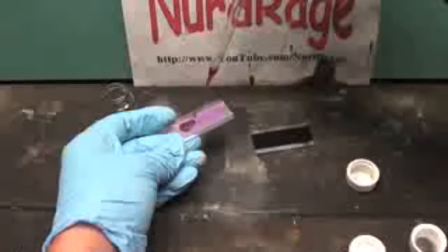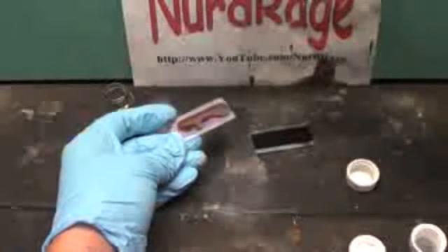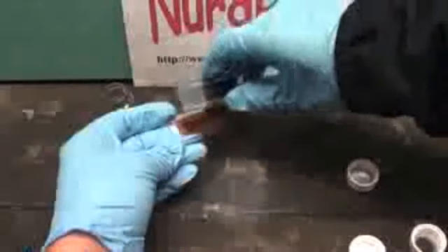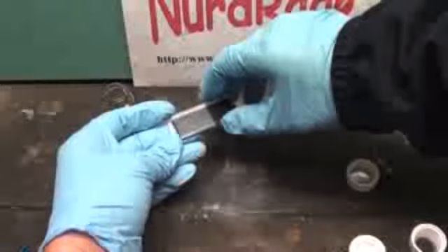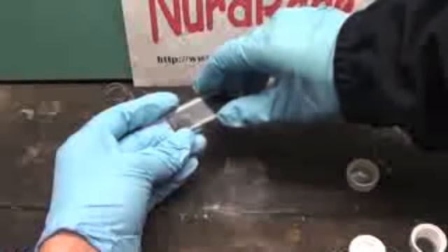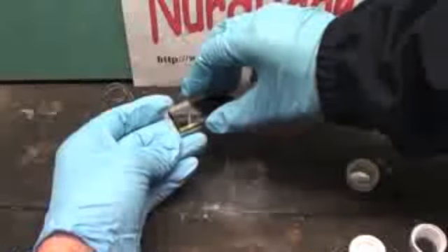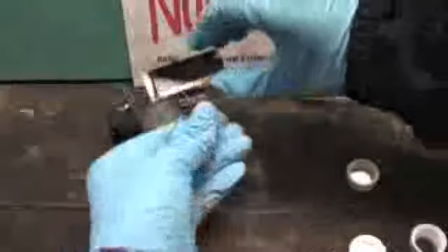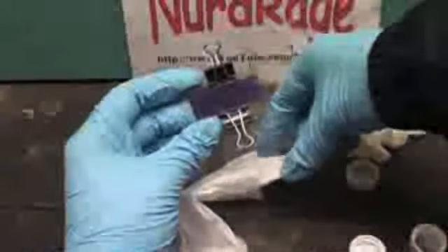Now for the assembly, place a few drops of the electrolyte solution onto the dry titanium dioxide coated electrode. Oops, I think I used way too much. I'll dab it off later. Now place over it the carbon soot coated electrode. Make sure the two sides with coatings face each other. Also be sure to offset the glass so that some of it sticks out on the edge. This is going to be our electrode contact. Now use binder clips to hold together the assembly. Since I used too much electrolyte, it's oozing out the side, so I'll need to dab off the excess. And it's done. Now we're going to test it.